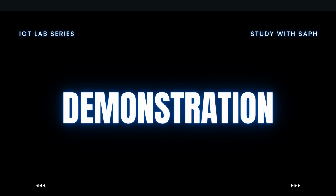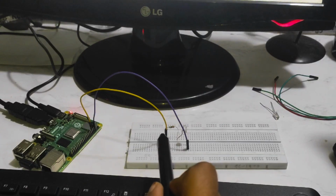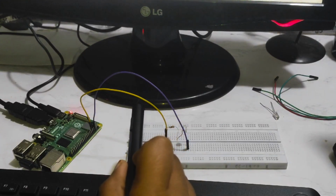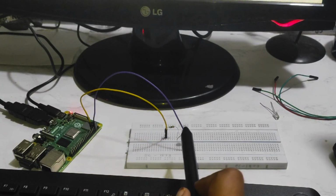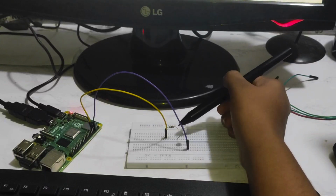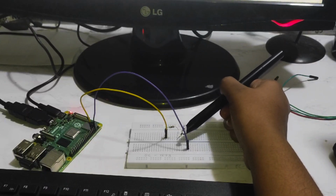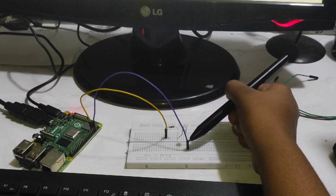Now coming to the demonstration part. As per the circuit diagram, these connections have been made. Yellow is the GPIO pin 4 of the Raspberry Pi and purple is connected to the ground pin. One end of the resistor is connected to GPIO pin 4 and the other end is connected to the anode of the LED, and the cathode, the shorter leg, is connected to the ground.